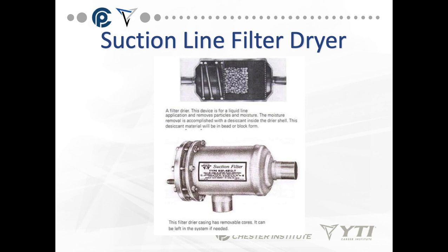Sometimes we put a suction line filter dryer in. Okay, a suction line filter dryer, again, is very directional and has a removable core. The reason we use these is if we've had a compressor burnout in a large system, we might still have acid and contamination in the system. So we want to capture that before it gets to the compressor. So we use it on the suction line between the evaporator and the compressor.